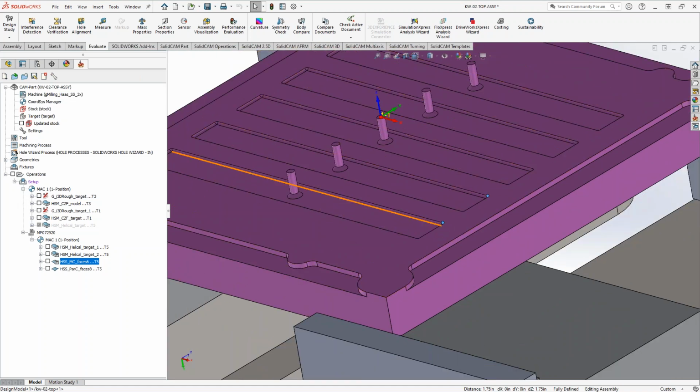The only time you have to do that is with rotate, translate, or fourth axis indexing. You need to know the exact amount you're moving it. The only time you can avoid that is when you use coordinate system transform. If you're going from one coordinate system to another, one part to another, then you just need to select the coordinate system. As long as that coordinate system is oriented the same on every part, then you don't need to know what distance those coordinate systems are apart, because now you're just translating by the coordinate system.